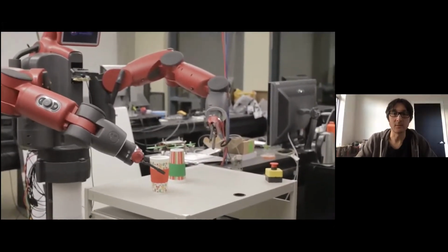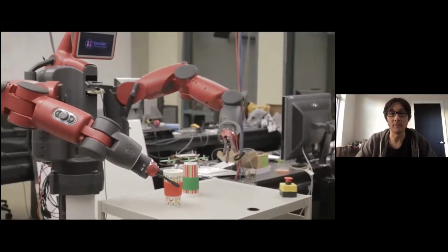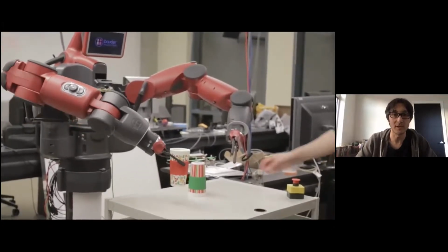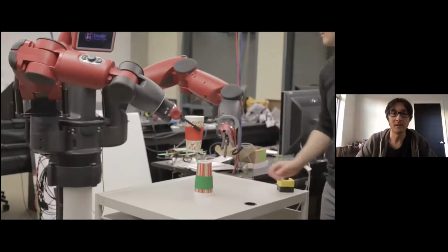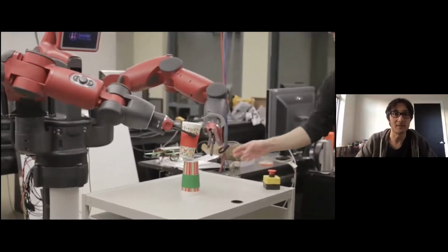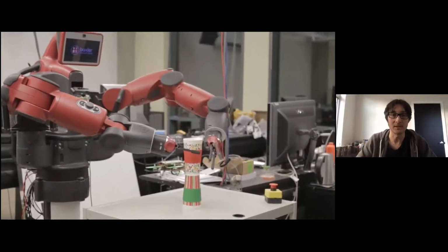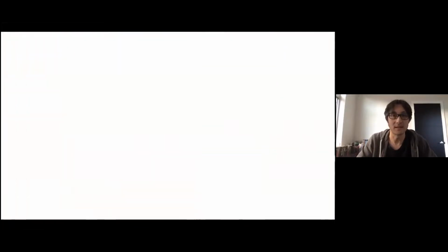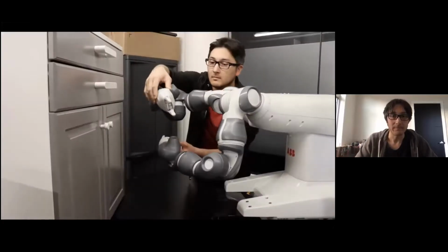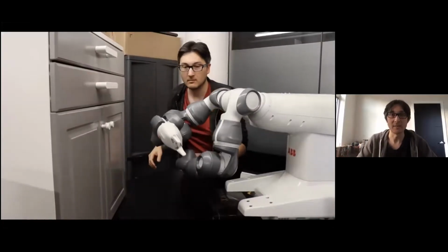And once it grabs the cup, it actually becomes part of the arm. And it's using a real-time tracker to track where that cup is relative to the end effector. So when I perturb it, it automatically, immediately reacts to it. It's running these things at a kilohertz internally, so the bottleneck is mainly perception there.